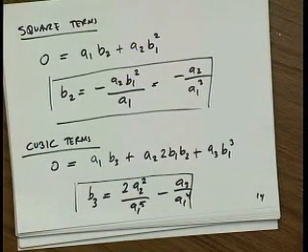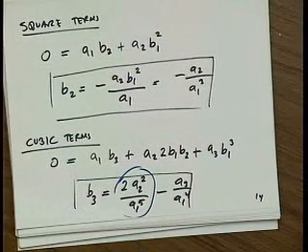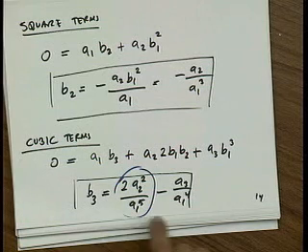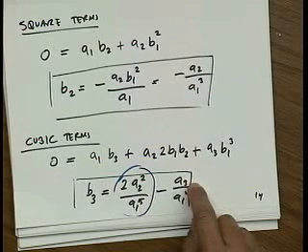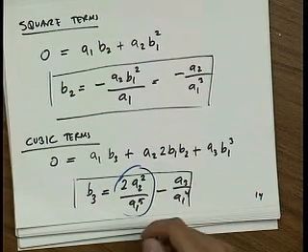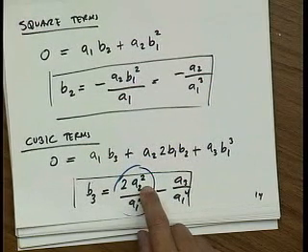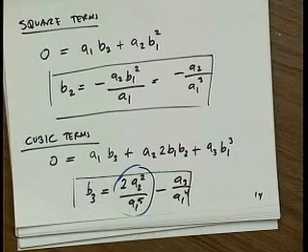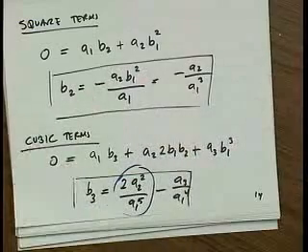What's also really interesting about this equation is this term. What's interesting about this term? Well, let's say our original relationship had A3 equal to 0. Okay? That means that in the inverse relationship there is no cubic term. When I invert that equation, though, boom, I can have a cubic term. So A2 interacts with A1 and produces a cubic term in the inverse. So just because the amplifier output to input relationship doesn't have a cubic term, doesn't mean that the inverse does not.